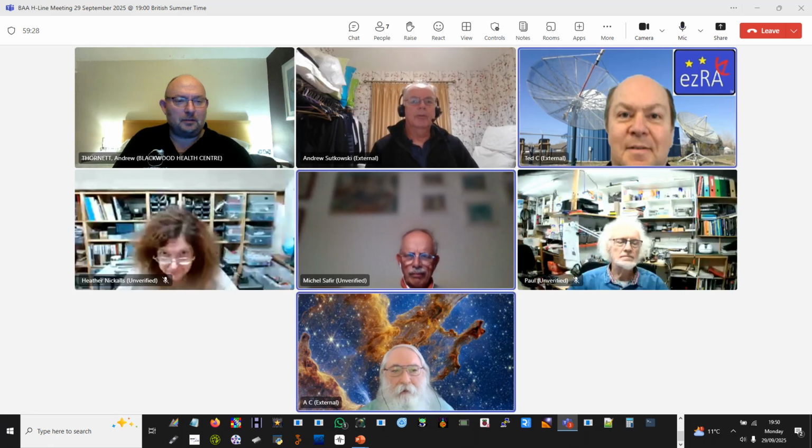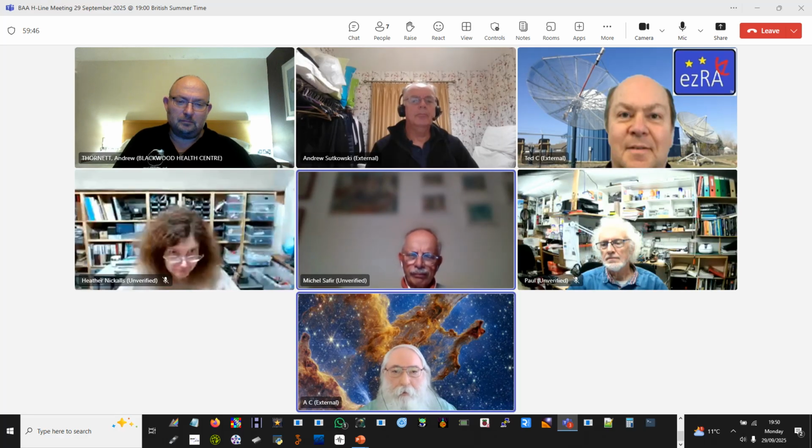Yeah, for hydrogen. There's a nice thing about it, that it does have the input and output for the clock. So actually, if you really wanted to go to the full 10 megahertz bandwidth, you can get a second device, and you can clock both of them together synchronously by using that output clock from one as the master into the input of the second one, and then you can run each one individually at the full bandwidth.